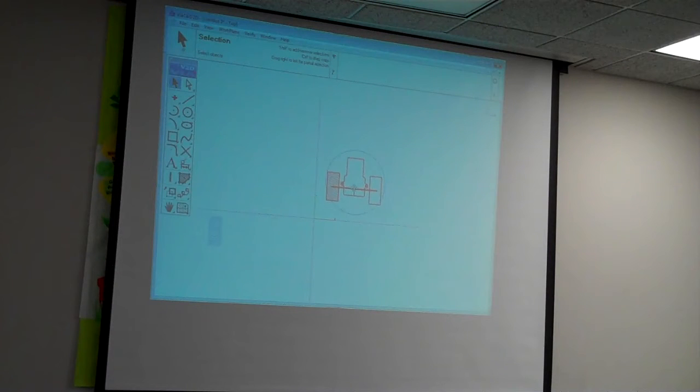And I can see that actually that circle is going to be a bit too small, isn't it? So let's go back in. Select that circle, and we'll delete it. Now here's where some of the drafting stuff comes into play. I'm going to do the same circle, but I want that circle to be centered on the midpoint of the axis, right? So when the robot spins, it's spinning exactly on its center. So I'm going to start my circle from the midpoint here, and then just draw it out until it looks to be about what I want. So maybe we'll say right about there.